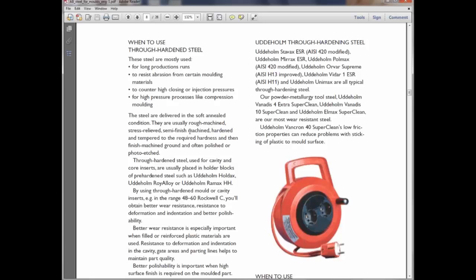To counter that bend, we leave some extra material, so that when we bring the part for machining, we will first clear that bend, and then go for the finishing process. Here residual stresses are not the issue.